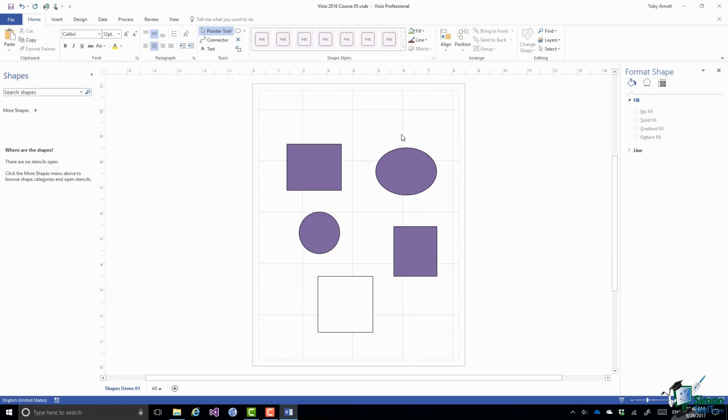So let's suppose I want to just select 2 of these shapes, the circle and the oval. I'm going to start drawing here, click and draw, and lasso the shapes that I want to select. And when I complete my lasso, you'll see that my selection now only has the circle and the ellipse in it. They're the only ones with that selection bounding box.